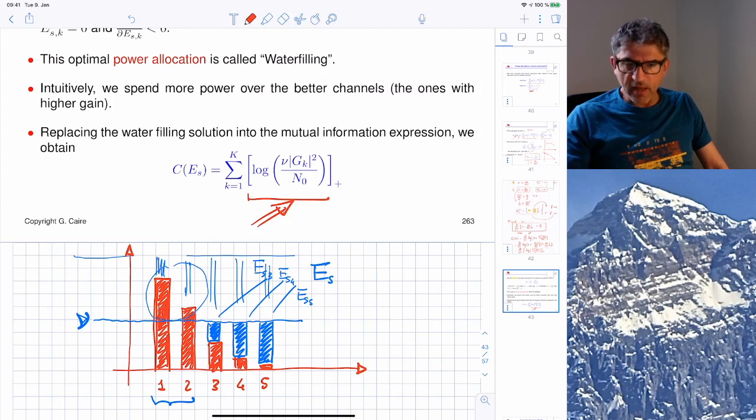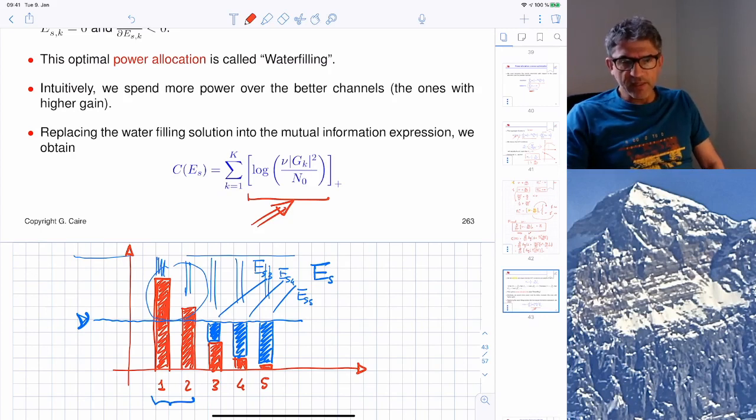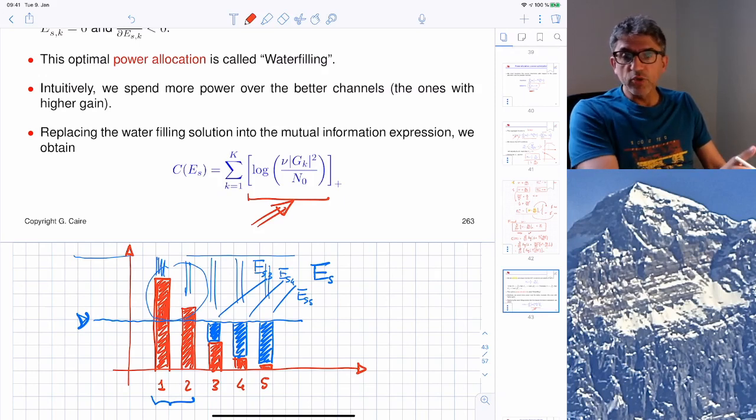In DSL, basically, in a way that we are going to see in a second, we can decompose the transfer function that represents the transmission cable from transmitter to receiver into a set of parallel channels in the frequency domain, and then we can do the bit loading over these subchannels, and this allows to achieve very, very high rates, hundreds of megabit per second on the same copper wire